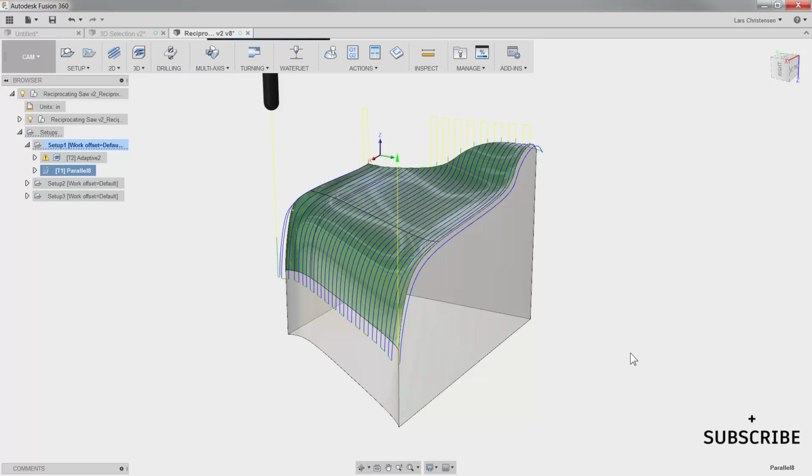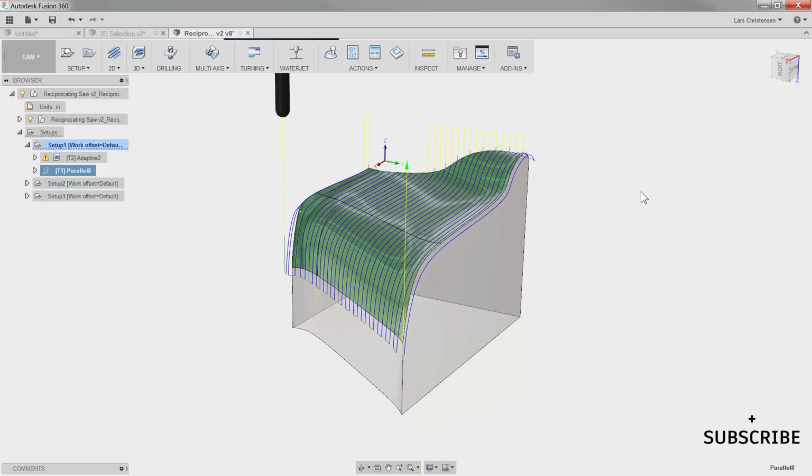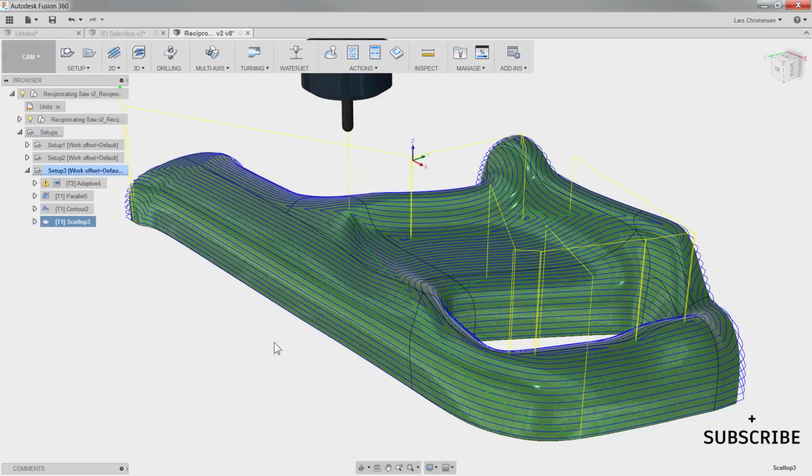And now we have a really nice surface where the tool will come down right to where it's touching on that edge and will go back and forth. This will give you a very nice 3D surface. Now the last tip I want to leave you with here is for this scallop toolpath. Remember that I said that it kind of collapses from the outside and in towards the center of the part. It really creates a nice step over. But there is a very powerful tool in there.